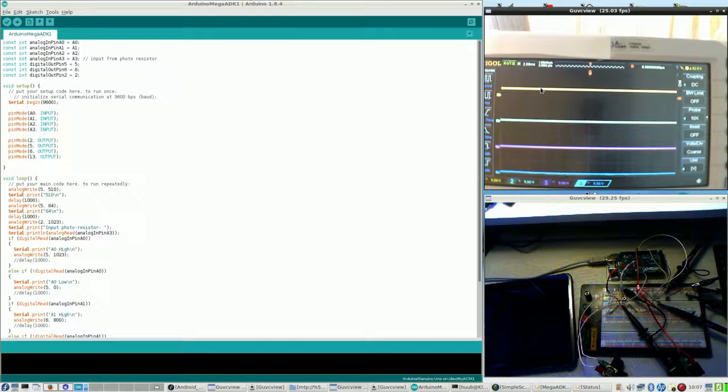So I put it newly into the schematics, and I thought it to be wise to put a voltage divider in it, because lesson learned with the Raspberry Pi 2, I blew up the port.